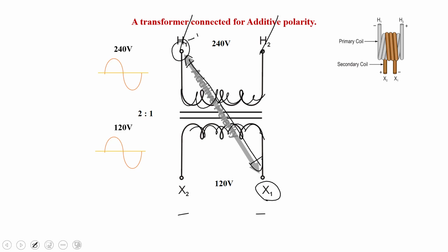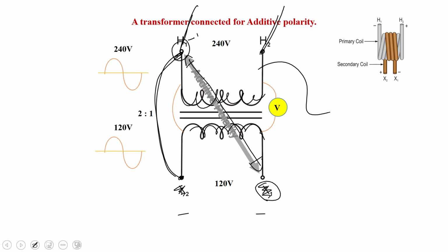And we do a little test on transformers. When you get here to do the lab, we are going to be doing transformer polarity testing. And what does that look like? Well, we take supply voltage and we put it across the H1 and H2 winding. And then we put a jumper from H1 to its adjacent terminal. So we don't really know what's happening here yet, which lead is labeled as what. So we jumper it when it's live. And then we put a voltmeter across from H2 to its adjacent X terminal. And then we'll energize it.